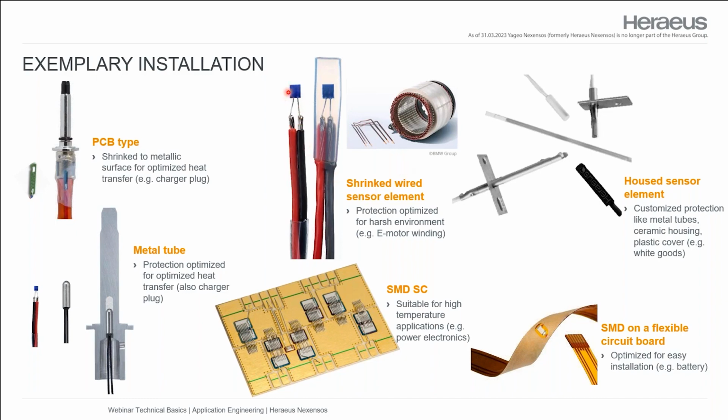We take a typical wired type, an M type, for example. We take a version where the wires are prepared for laser welding, because this is a very, very reliable interconnection technology. We laser weld this M type directly on that cable. Then we protect this system from the environment with a shrinking tube, but this is a very special shrinking tube. This is a shrinking tube with a melting part inside of the shrinking tube. That means this is really very well sealed.